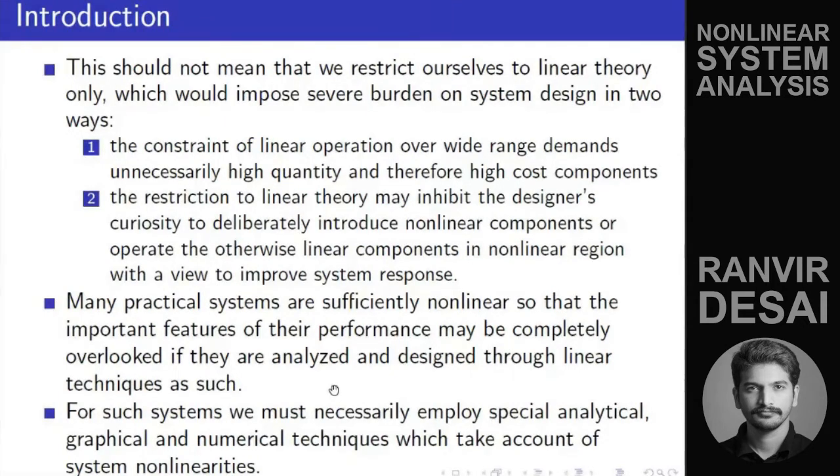In the case of a space aircraft, the accuracy or the tolerance is even tighter. Let's say a 1% design error could be tolerated. After that, even if you say that yeah, I did my best, it was a 97% accurate model, that control system will not control your actual aircraft if the modeling error is 3%. You need to consider this.